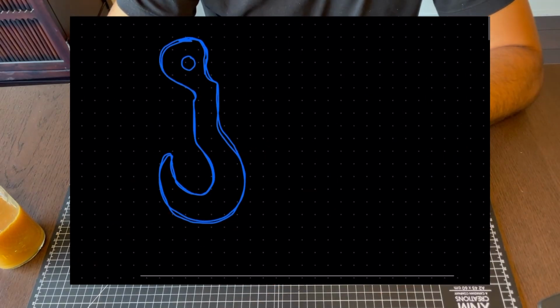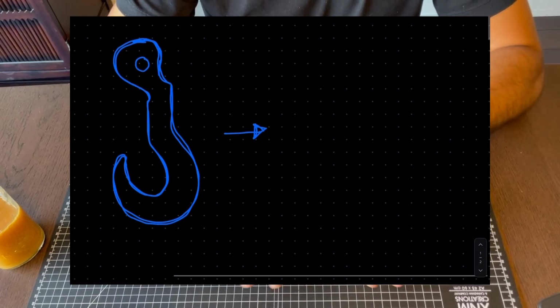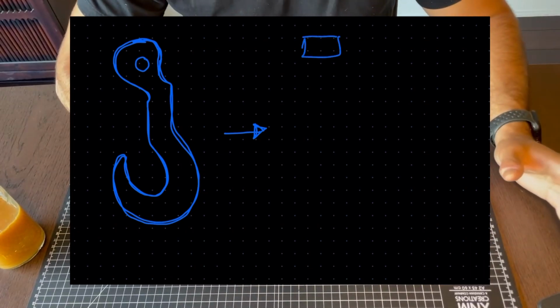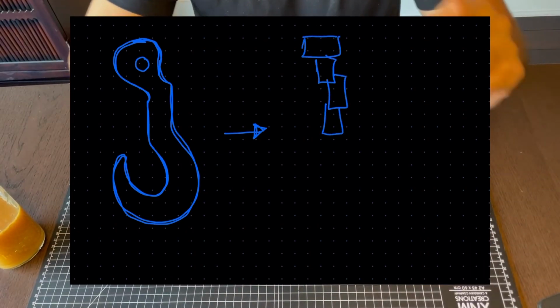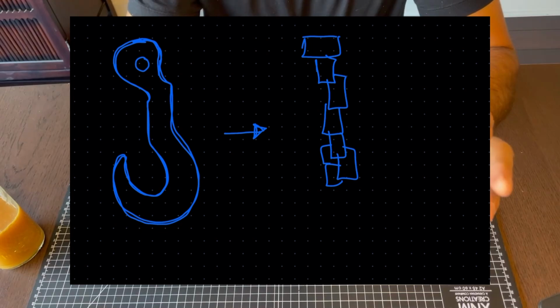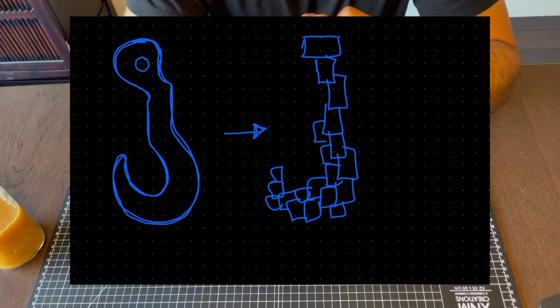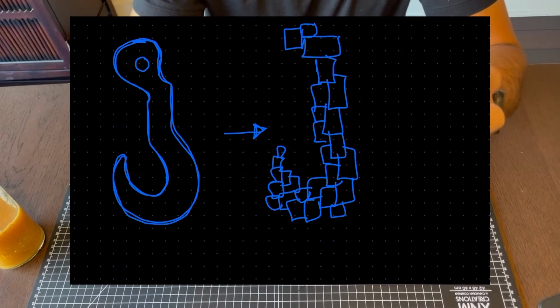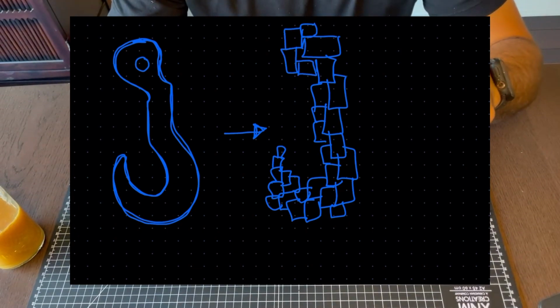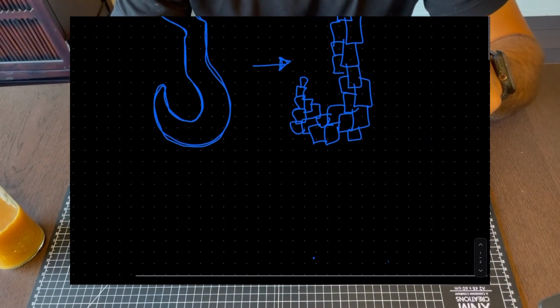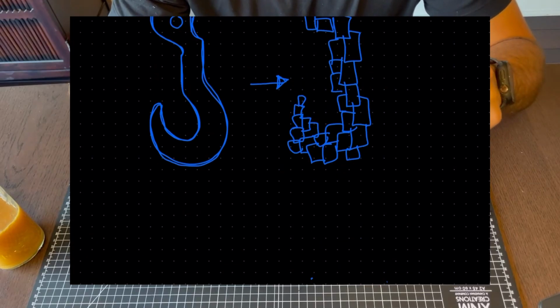First step, you're going to need to do something called a finite element analysis. What that means is that you convert this part into very tiny blocks, for example. And each one of these blocks represents a section of it. And it's a cube, it's in 3D. It has 6 sides, it has 8 corners, and it's connected to other blocks or the air. You can imagine that each one of these blocks has a sensor, each one of its corners or its sides.